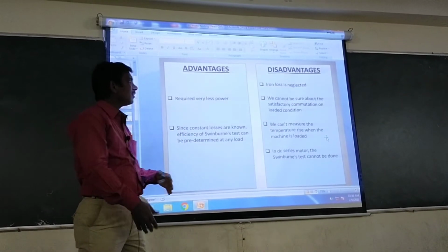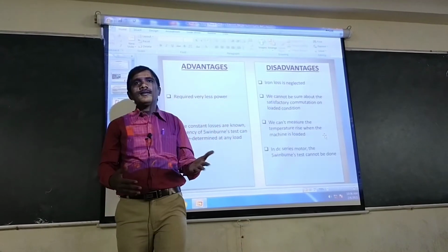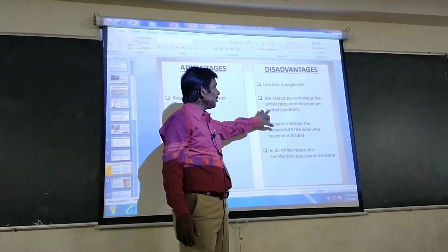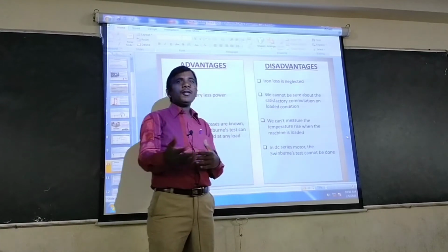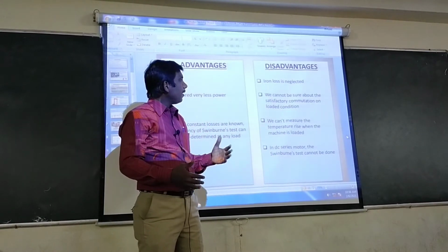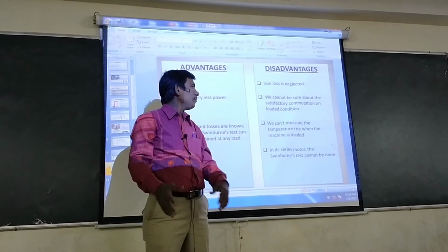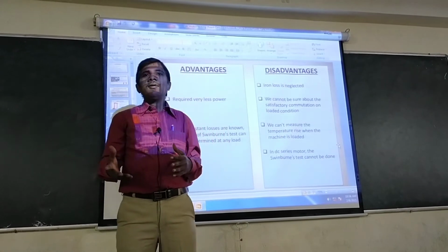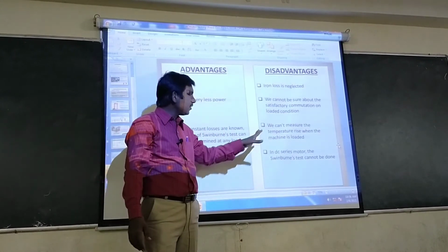Some disadvantages are there. Iron losses are neglected in Swinburne's test, that is one of the disadvantages. We can't give surety that commutation will be satisfactory under loaded condition. We can't measure the temperature rise when the machine is loaded, because the test is conducted at no load. These are some disadvantages.